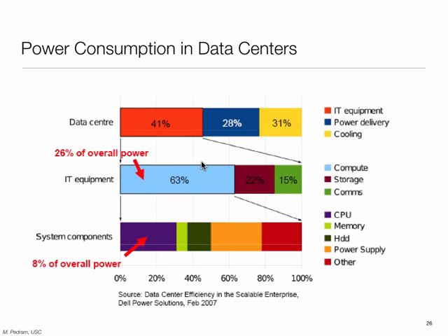Clearly, if it is supplying zero power, say I just shut down my computer, then it's infinitely inefficient, still consuming some energy. And if it is supplying a very large amount of power, because I'm running some heavy-duty stuff, again it will be less efficient. The peak efficiencies are around the mid 80s or so. What that means is that even in a system like this, 15% or so is being wasted running the system. Then there is wastage within the laptop itself as well, because this voltage has to be cleaned up and things like that.